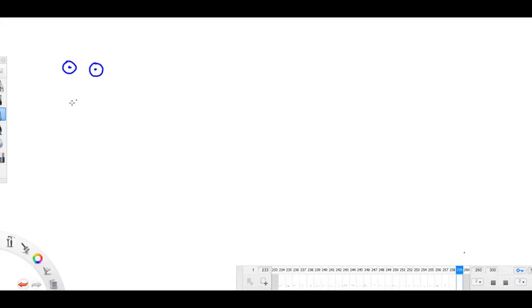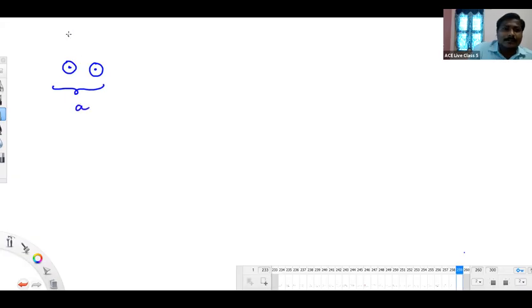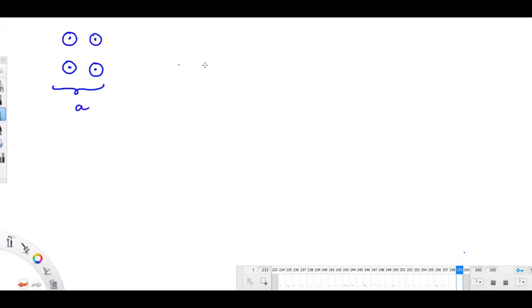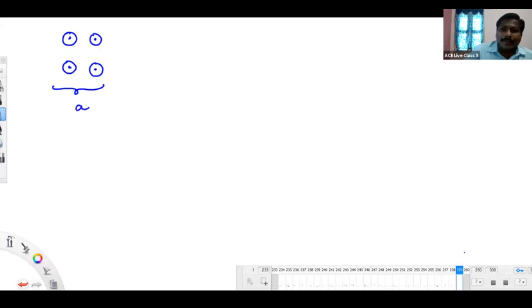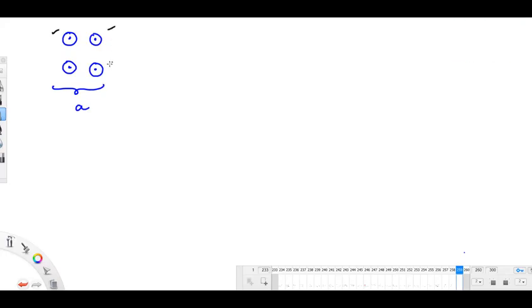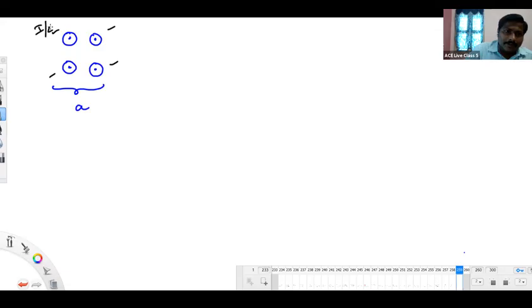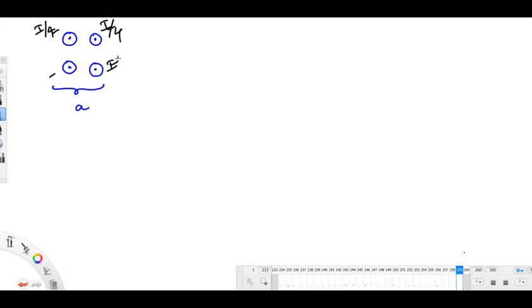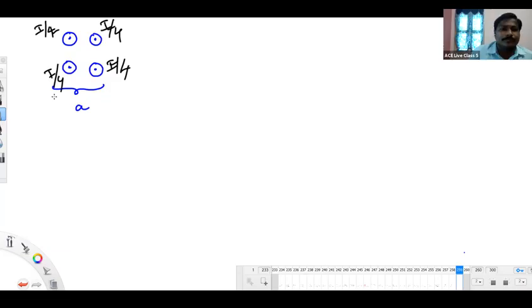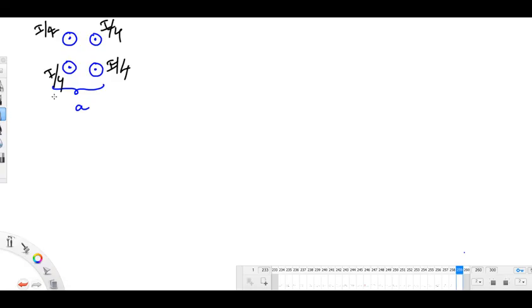Suppose there is bundling of the conductor. In one phase, there are suppose 4 conductors, and this is the second phase. Phase A, yes. Okay, 4 conductors. Next, tell me. Yes, and suppose the current flowing in the first conductor is different. Listen, stop. If all the 4 conductors are of equal size, then definitely each and every one will carry I/4 current, because all are running in parallel, connected to the same bus bar, right? The current is getting divided equally.